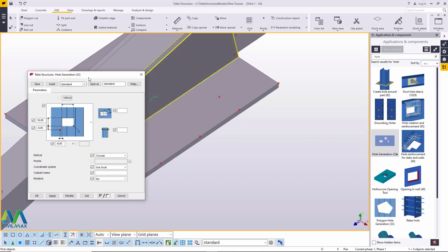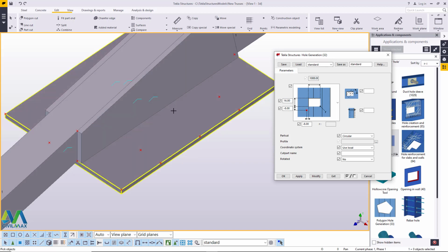I'll double click on that macro here, and I had done this previously. So if you want to use an M16 here, the hole must be slightly bigger by 2 millimeter. In this case, we'll feed 18 there, and we'll use half of this 18 and prefix that by a negative sign. We'll feed there 9, and also we'll feed here 9 millimeter. And what do we do? Our hole will be circular.